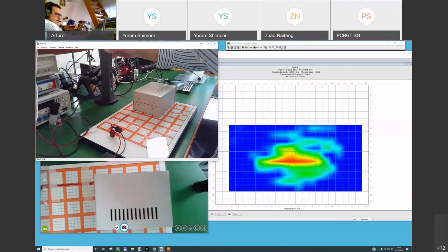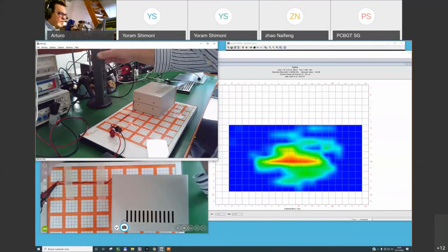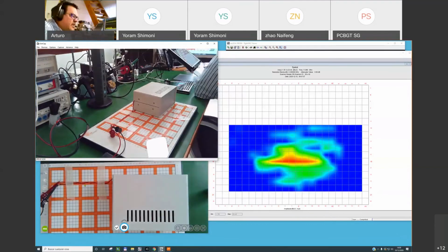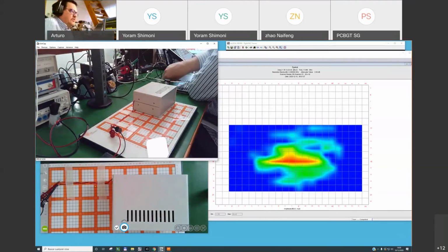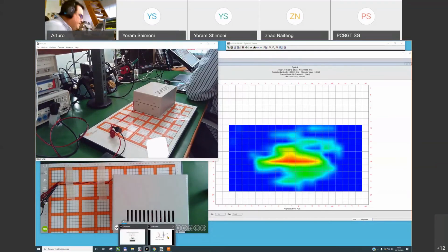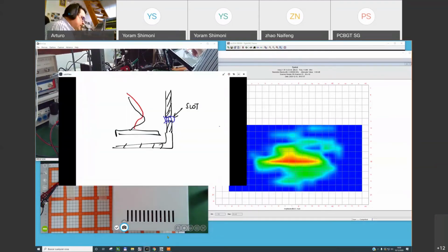Now I am interested not in the enclosure. I am interested in this cable. When interested in radiation from cables, you need to remember that energy in cables can run in common mode or differential mode. Let's go to the notebook here. Let me introduce another sheet.